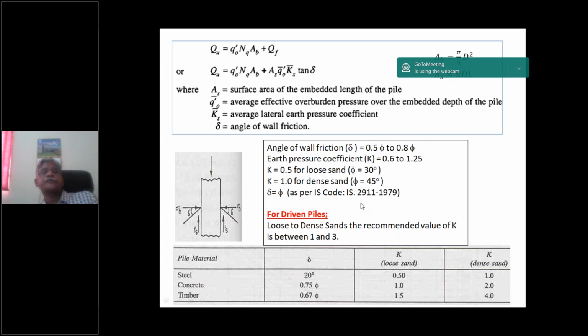So in case of cohesive soil, such as saturated clays, the angle of internal friction phi will become 0. Accordingly, the Nq value equals 1 and N gamma equals 0. So the formula will be simplified further.